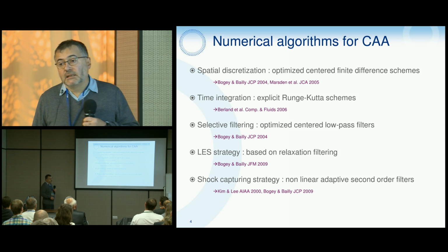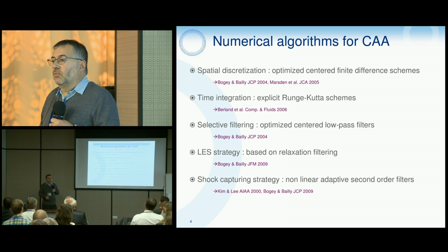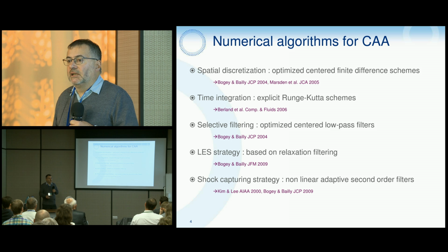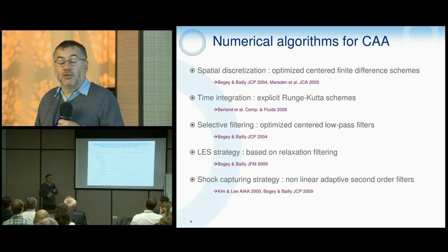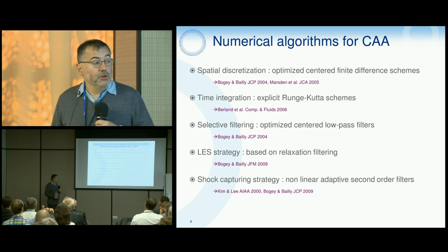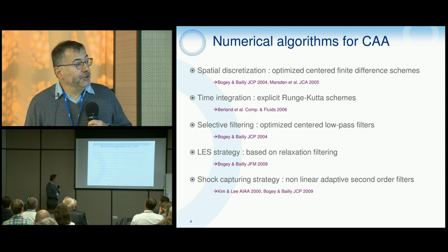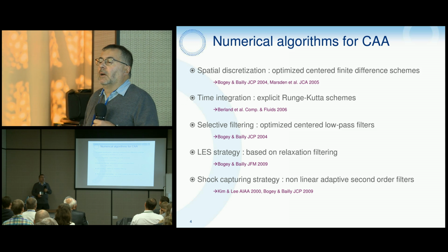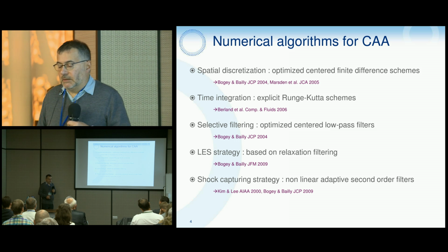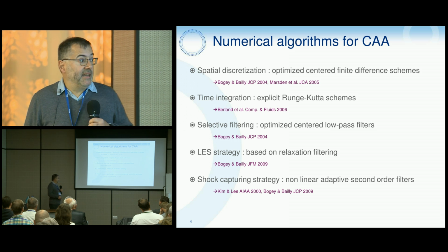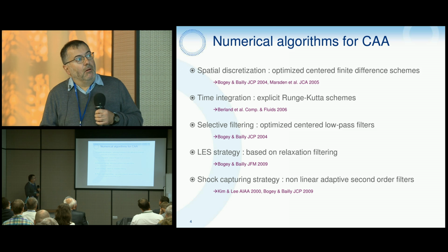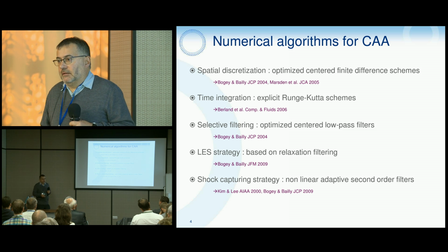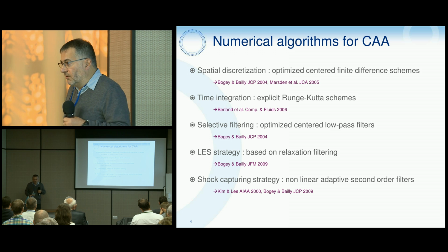We use the Kim-Henley approach, which adds a kind of hyperbolic viscosity in order to capture the shocks. The approach of Bogey and Bailly is more of a filtering strategy without any hyperbolic characteristic inside. So I think that now all these features are quite classic in the area of aeroacoustics.